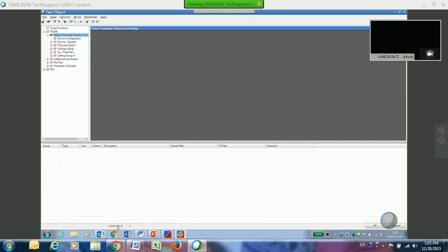If I had any warnings or any errors associated with that, I would want to go back and check these errors and warnings out and make sure that there's nothing major affecting any of my relay settings. Sometimes it's not, sometimes it is. It's also going to show up under this type. The type will say whether it was a warning or an error. By just clicking on any one of the lines that are here, it'll jump you to where that setting is on the screen, and you can go in there and look at the values and change them and fix them if you want to.